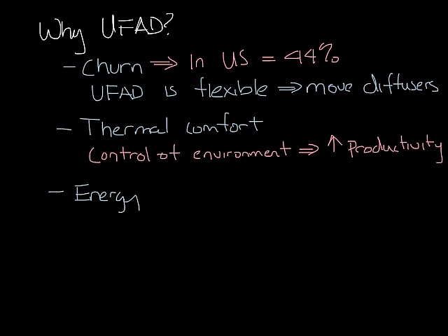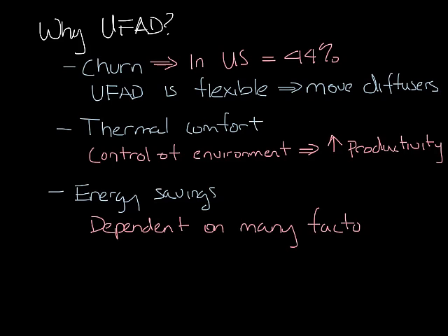Energy savings is a big reason to use underfloor systems as well. When LEED started gaining popularity, a lot of buildings that wanted LEED certification looked at underfloor systems. But there are a lot of factors that determine whether you'll save energy using a UFAD system. One of the most important ones is climate. If you're in a mild climate, you'll probably see the biggest savings. This is a topic all by itself, and we're out of time, so I'll probably cover this in another podcast as well.